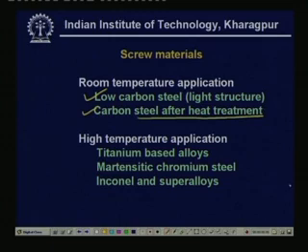There are various processes of heat treatment, and these are all specified in standards. So when you have to design such a threaded fastener, you'll have to look into the standard. There are different material standards, and medium carbon steel with different kinds of heat treatments is possible. Quenching and tempering are the two most frequently used heat treatment processes.